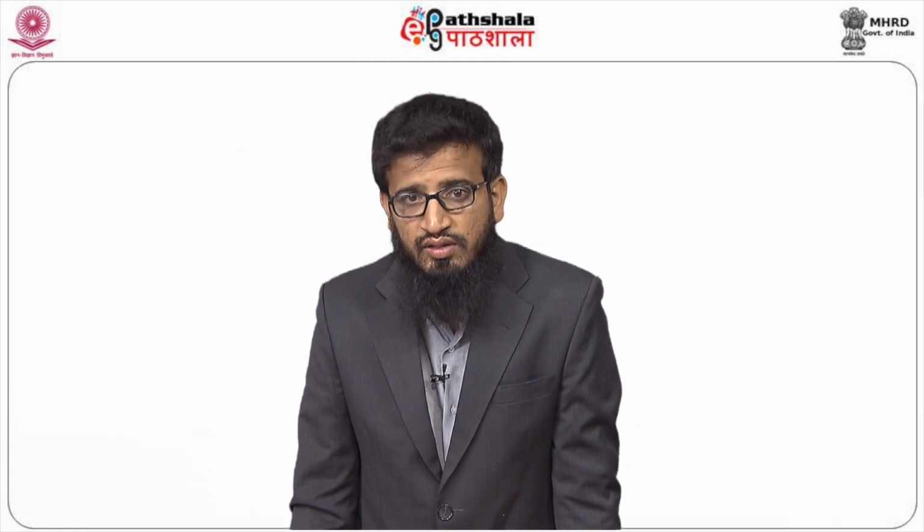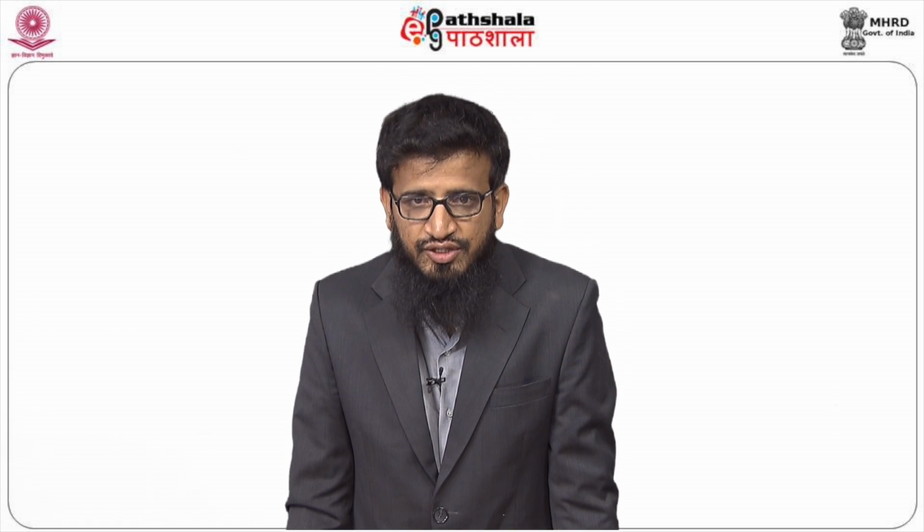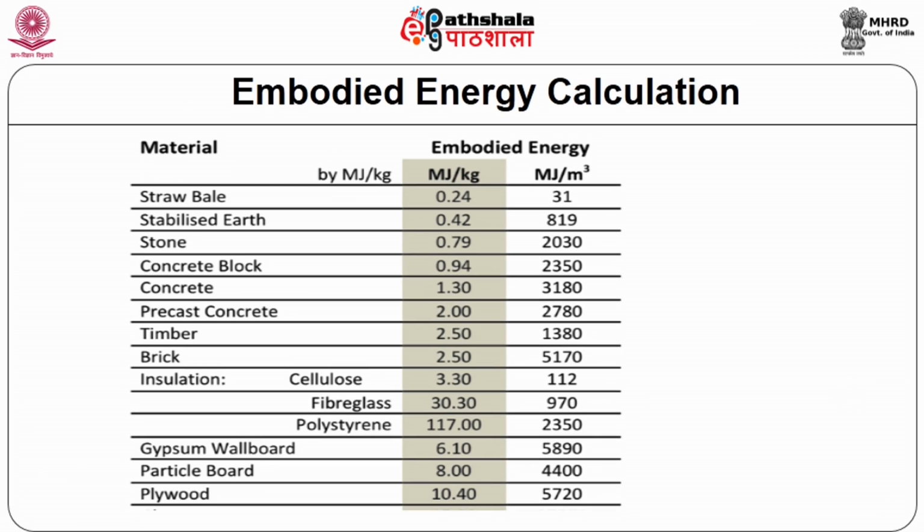Since we are using brick, you can see that it is 2.5 megajoules per kg, or around 5170 megajoules per meter cube. The difference between megajoules per kg and megajoules per meter cube is that megajoules per kg is based on your density, so you get your volume, multiply by density, and calculate the mass. But megajoules per meter cube is calculated directly based on your volume rather than your mass. So these are the 2 methods that go into it.